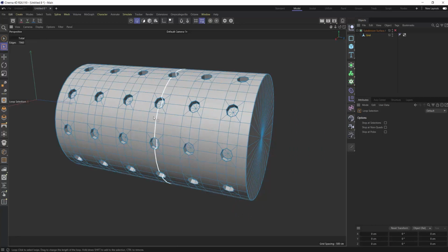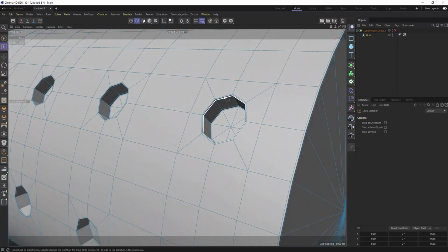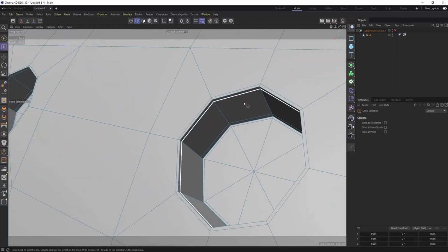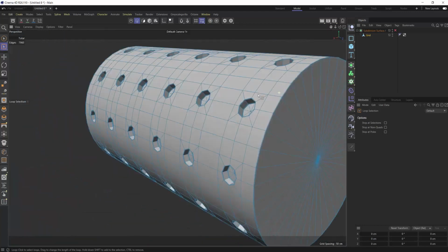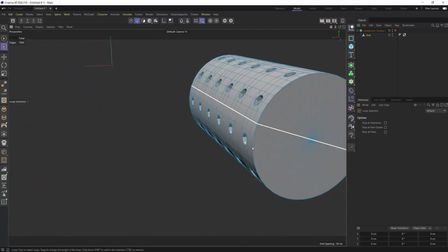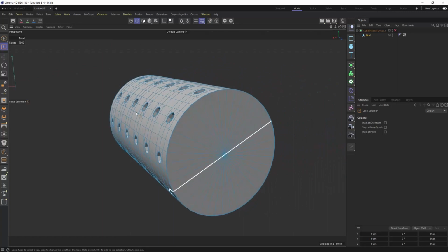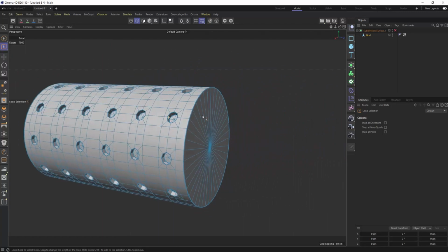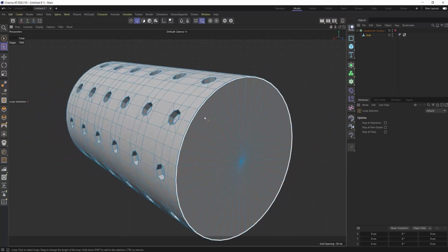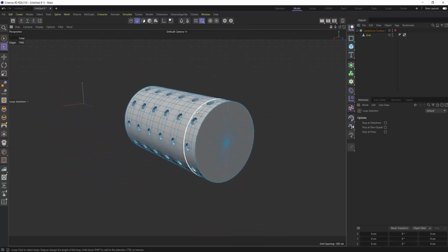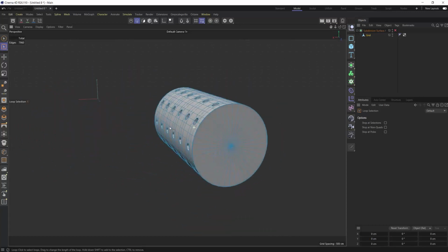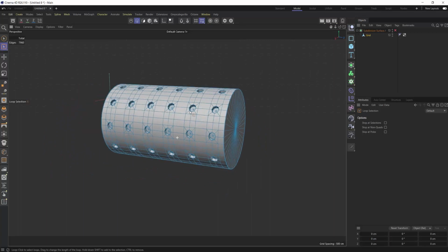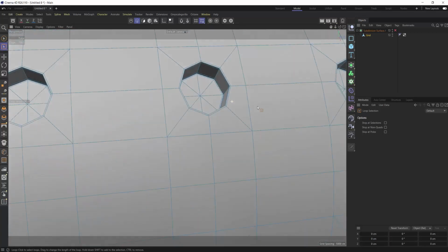Now, we could probably still easily deform this with a bend deformer, but the way we've created it is all with hard surface modeling techniques. And the reason we need these additional rotational segments is because we're working with a cylindrical shape. That's why it's a little bit heavier as far as the segments go, because we need these rotational segments in order for it to be a perfect circular shape. But this is still hard surface modeling here.